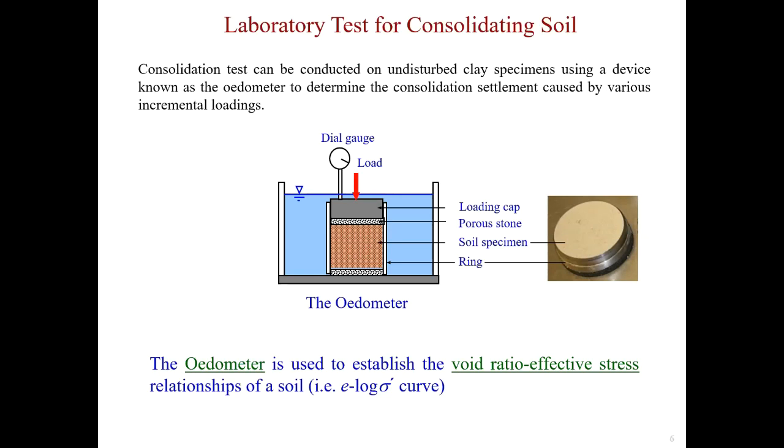And we are going to simulate loading it with an induced stress. So we take this clay sample and we put it inside a steel ring. Here you see we have a steel ring, and that's the intact soil sample. Then we put this steel ring together with the sample inside a water bath.